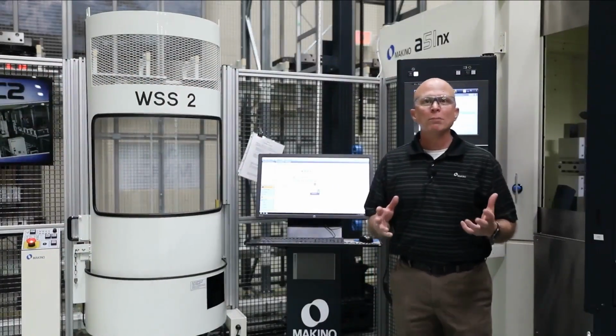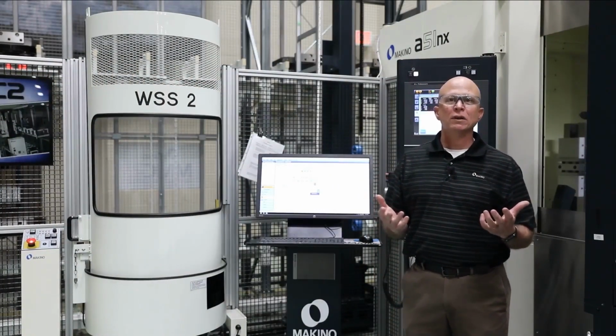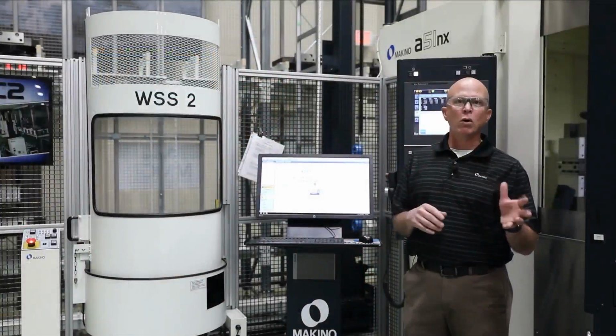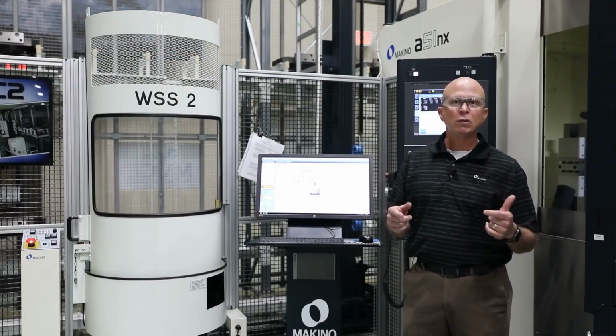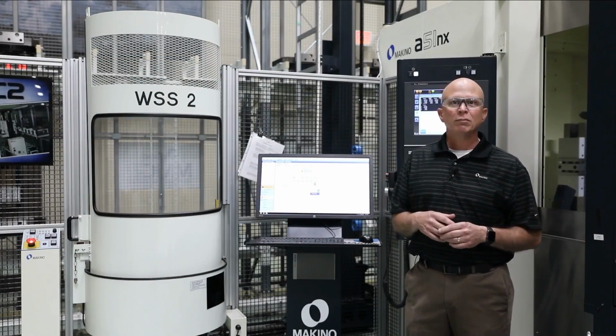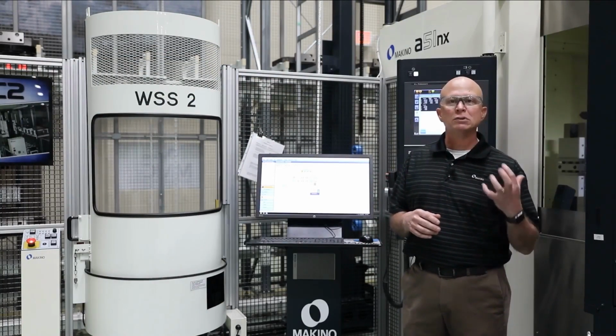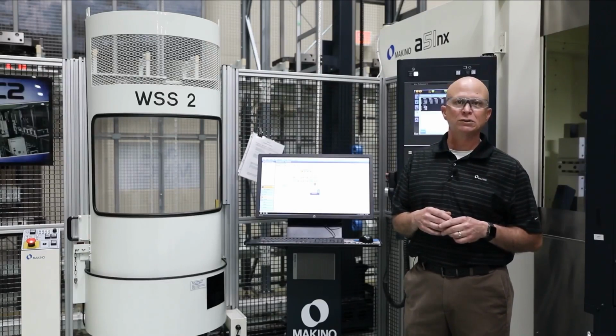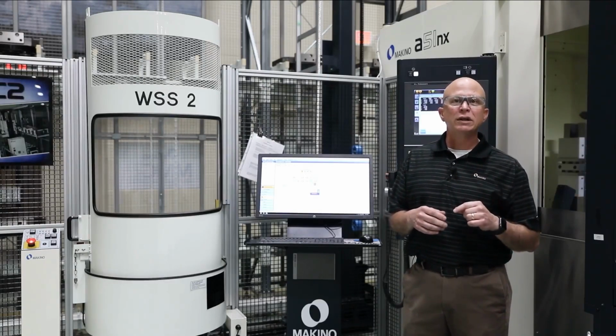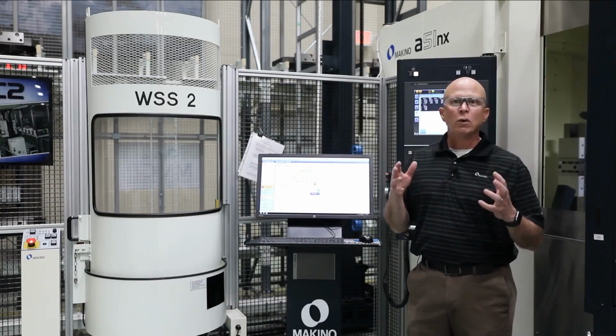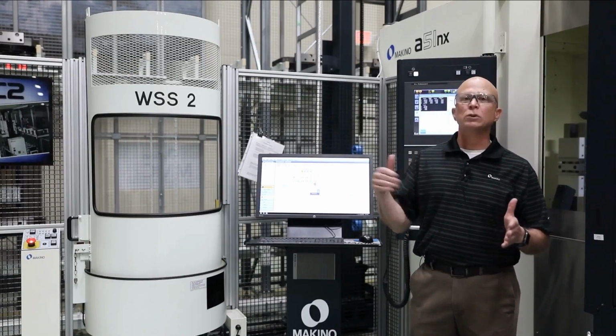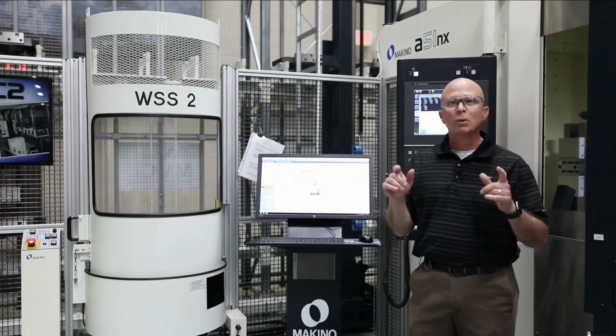So talking about program optimizing, we're going to set the stage here for this demonstration. We have a pallet set up on the machine, and you've got to visualize a 2-part fixture, a 2-nest fixture, one on each side. We're going to do some work on one side of each part. We're going to rotate around and do some work on the other. Again, this is looking at optimizing your positioning to and from the automatic tool changer. The first one you're going to see is more of a traditional way where you go over to one nest, do some work, go over to another nest, rotate, and just duplicate that exact tool path. So that's the traditional way.